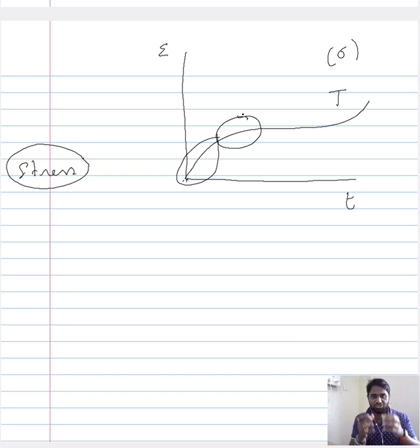So in the initial stage you have a combination of behavior that includes elastic, anelastic, and plastic. In the transient stage, which follows the instantaneous initial stage, the plastic deformation becomes dominant. However, the plastic deformation is confined to a given amount of load. There is not much strain that is possible, therefore the strain rate decreases. So in both these initial stages, we saw the stress is the dominant factor.